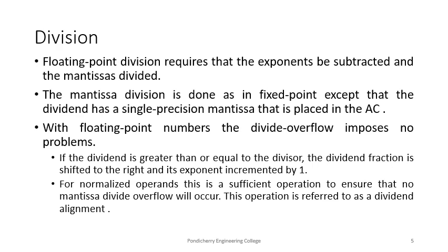Next we will see floating point division operation. Floating point division, similar to multiplication, requires the exponents to be subtracted. Since it's a division, we subtract the exponents and of course divide the mantissas. The mantissa division is done similar to the case of fixed point.